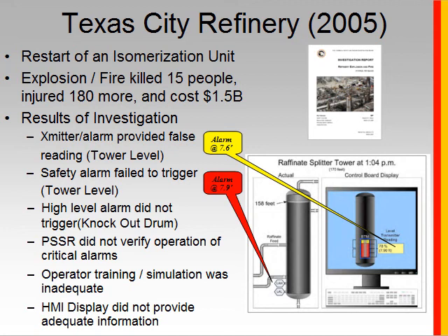false reading. It did trigger an alarm, but as the tank continued to fill and basically filled beyond the range of the transmitter, the presentation to the operator showed that the tank level was actually going down, when in fact it wasn't. It was going up and filling to the top. An alarm was generated, but the operator was obviously confused when you look at the screen and you see that the level is going down, but yet you have a high level alarm generated.